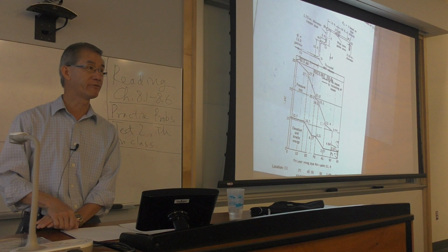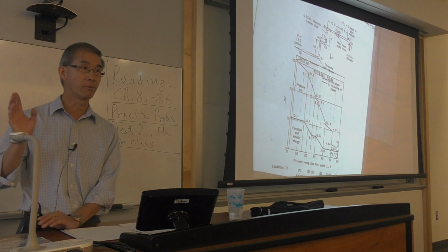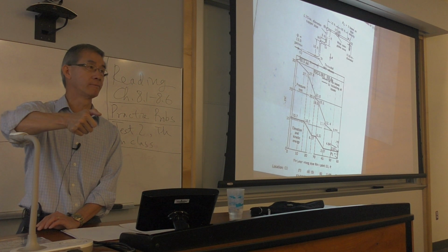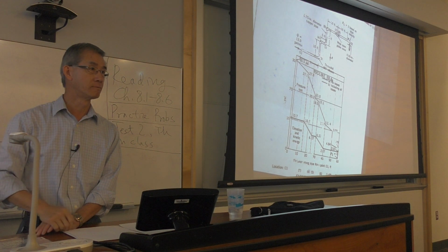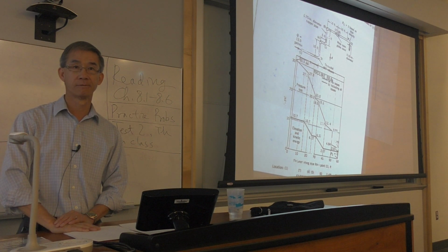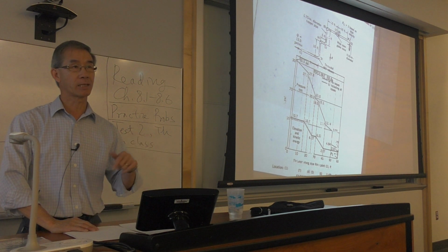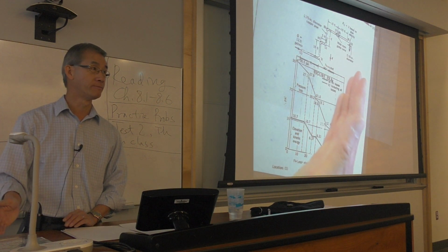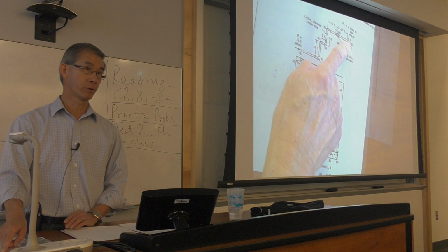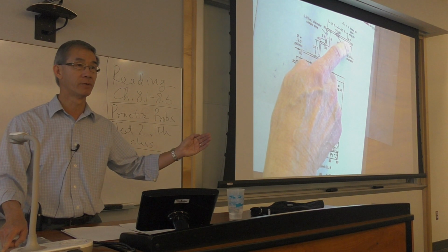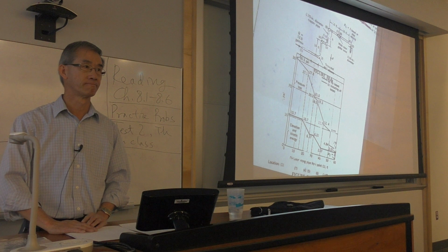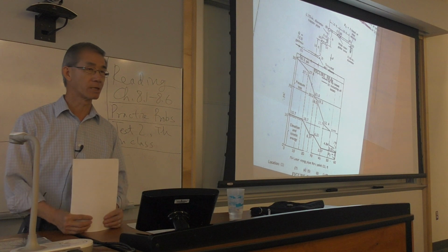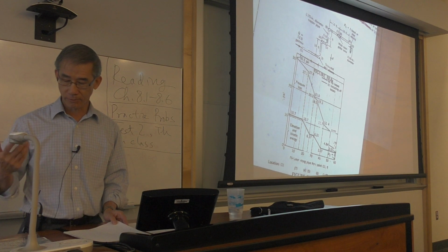It has a water hammering effect. And if you have ever seen that, if you want to be a plumber, you have to listen to this. When you open the water and you shut it, all the pipes rattle, they shake. Have you ever had that in your house? That's what this is. The water supply coming to your house is too high. And when you shut the valve, it creates a shock wave. The water stops and sends a pressure pulse within your whole house back to the valve, and the pipes resonate, they just shake. So it's not very fun when you flush the toilet at night. You wake up everyone. So this is for plumbing.